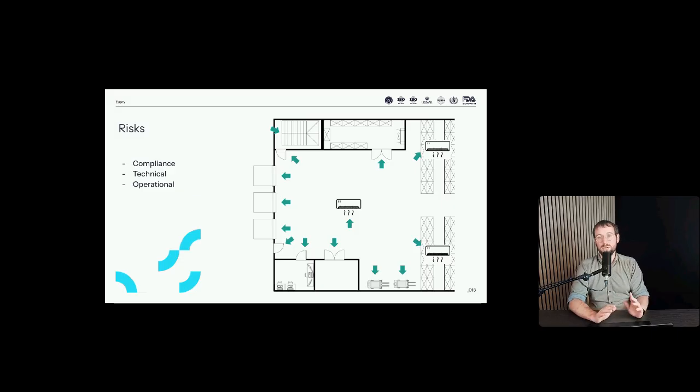And the same thing goes for temperature control trailers. How often do you plan to open them? Is it a one route connection you're planning to test for? So being loaded in one place, going to one other place and offloading, or is it dropping off products at smaller stations? Well, in that case, you need to ensure that when you open and close the doors, temperatures go back to normal within a certain specified amount of time. And the same thing goes for fridges and freezers.